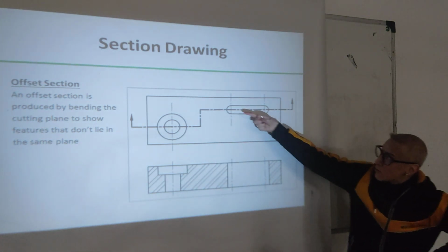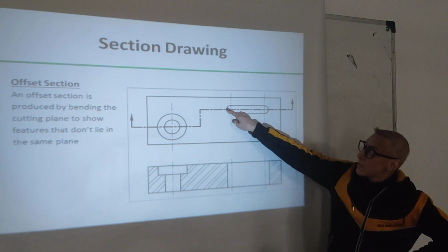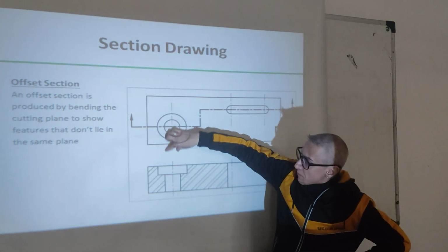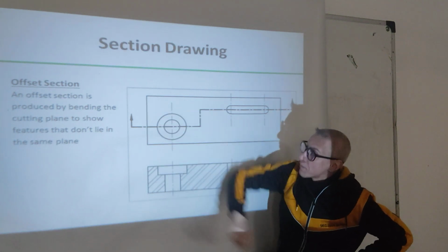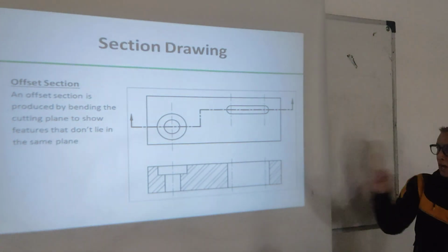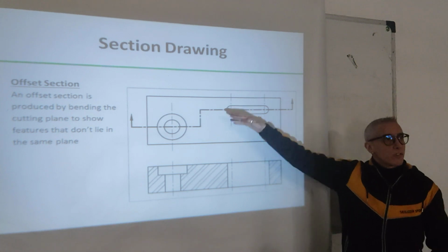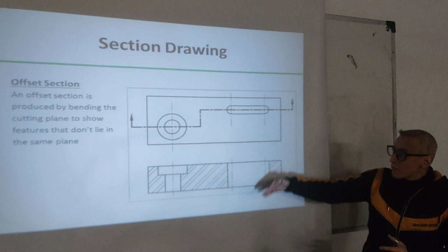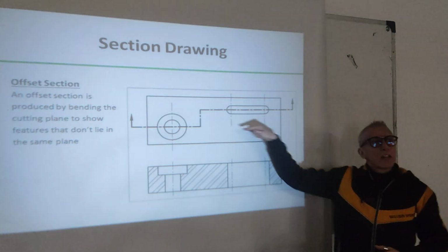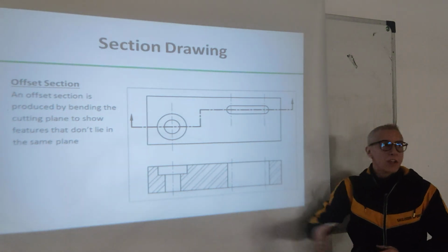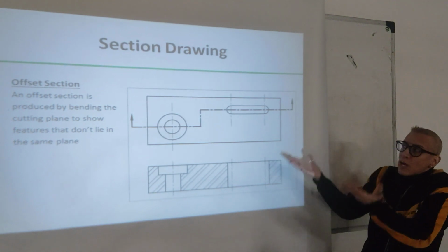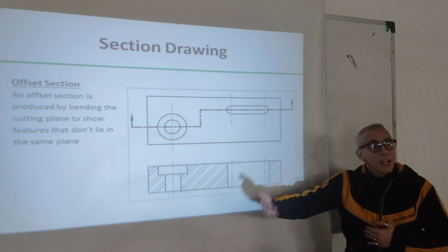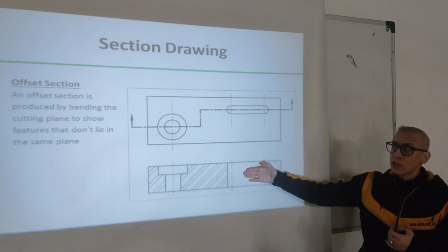Look, put two lines down. This is this object, opened here. And this here are these two. If you put the lines down. So, in one drawing, I show all of these interior openings of the object without having to draw two section lines and two open section views. So this is again to save you time. No need to draw extra if you can show it in one drawing.